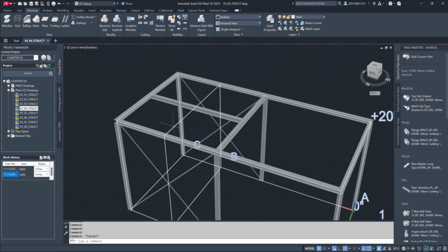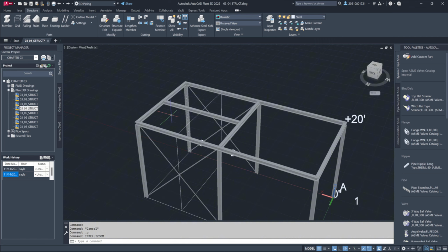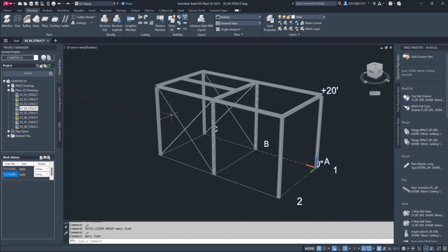But I want to ensure you're aware that after making a grid adjustment, you'll also need to manually modify the steel accordingly. Editing steel elements in parallel mode simplifies the process. It's essential to manually adjust the steel as necessary following grid adjustments to ensure everything aligns as expected.